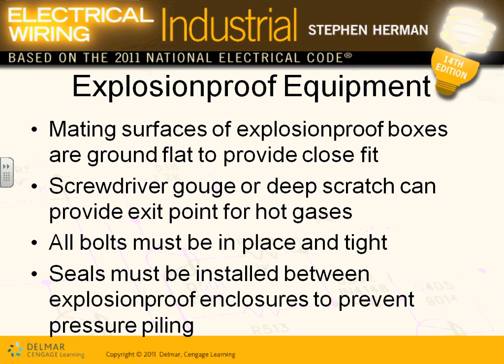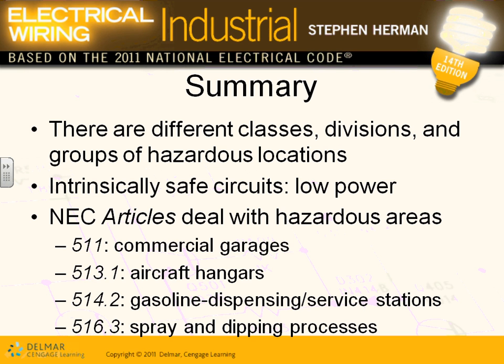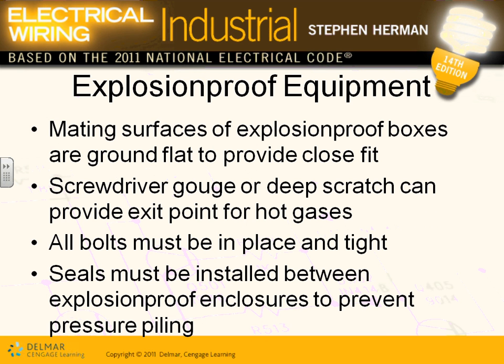For explosion-proof equipment, the boxes are ground flat to provide close fits. The mating surfaces of the explosion-proof boxes are ground flat to provide close fittings. You need these because the explosion-proof surfaces must be completely touching each other, with no niches inside. Why? Because you don't want the gas to enter or the explosion to leave the explosion-proof area.